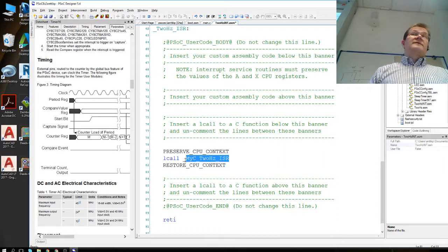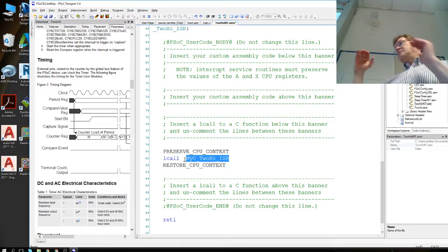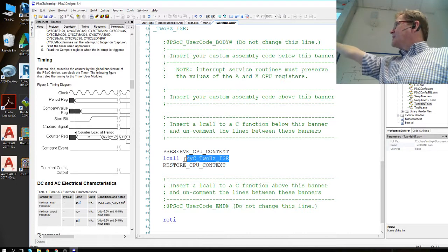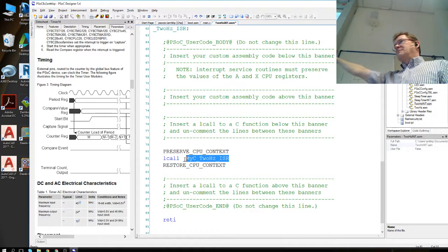I copied it without the first underscore, since the C compiler compiles to semi-assembly code where all the C variable and function names have an underscore in the beginning. That makes it easy to call any C routine from assembly.